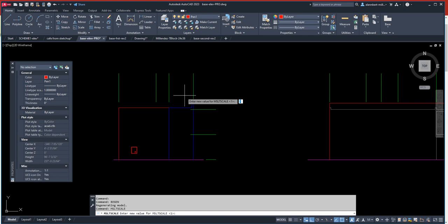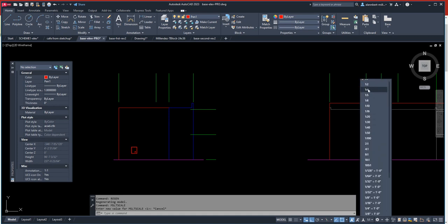When you set your MS LT scale to 1, it will adjust its LT scale according to your annotation scale, and the annotation scale is actually this box here or this setting over here. When you click on that one, it's set to 1:1. It doesn't change anything if we set it to a different one, but this one is an annotation scale. That means that if we change this, the LT scale value will adjust to what's appropriate for a 1/8.